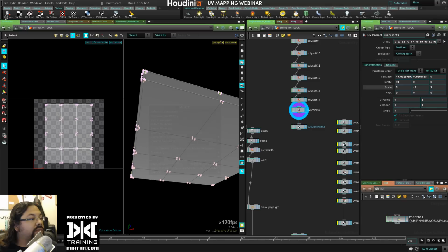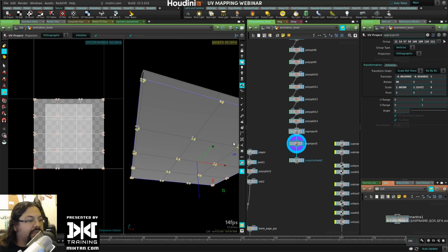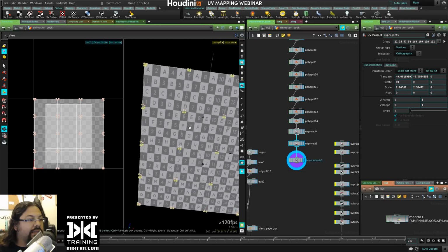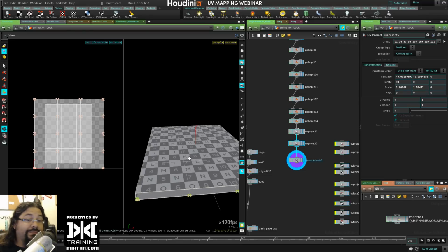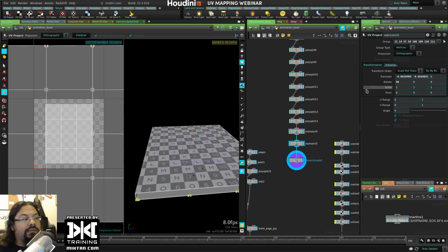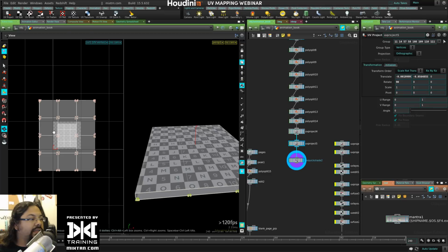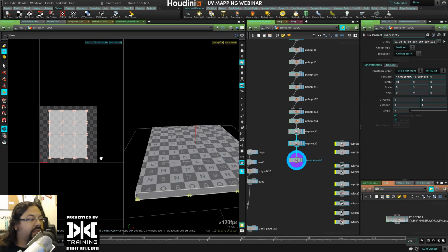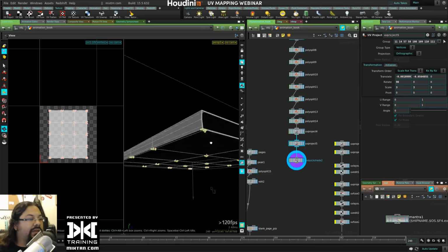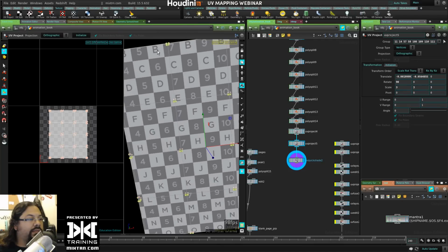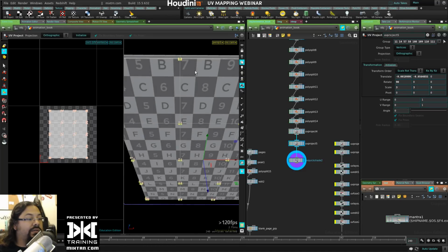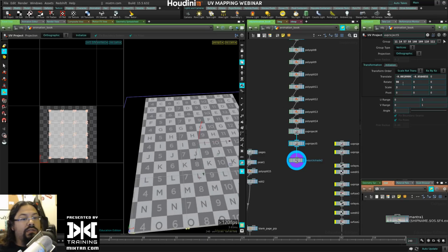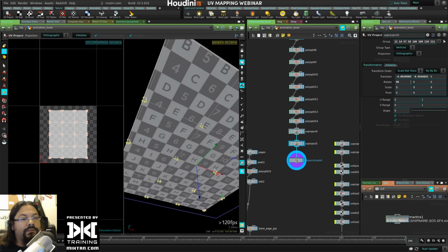and use the UV project again. Again, it's gonna project that. There's the UV. And they are flipped. Let's just reset these values to get the correct aspect. Put these 3. We did 3 with the other one, but now they are flipped. You can see the top here, and this is the actual top, but the UVs are pointing to the bottom. We're gonna have to rotate this.